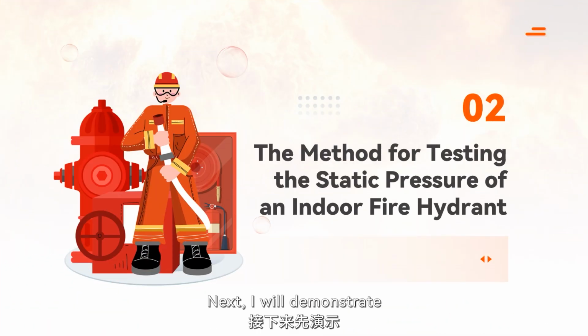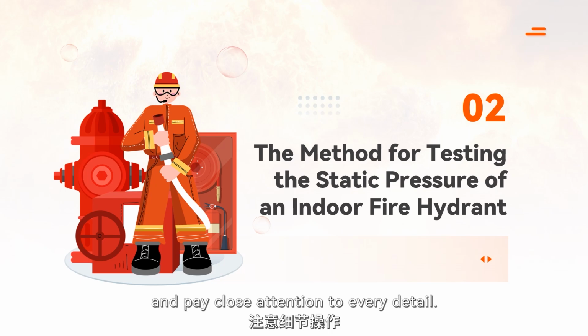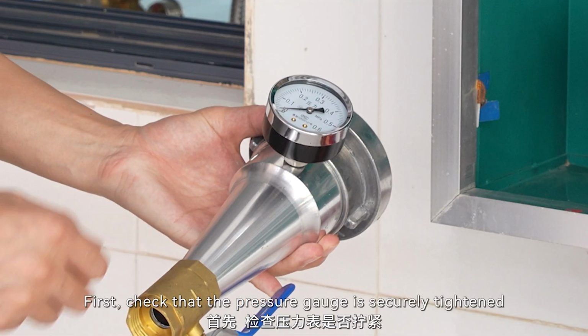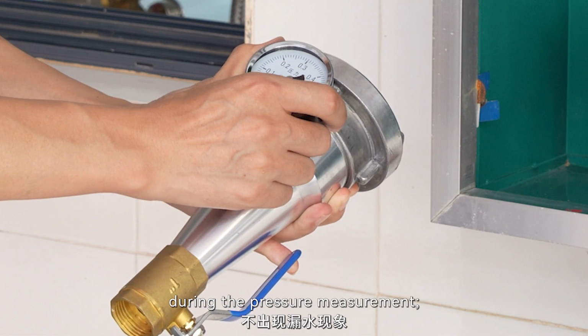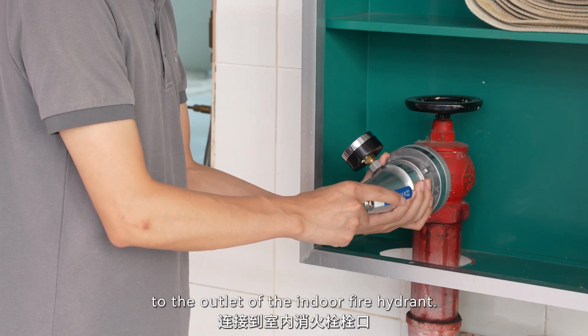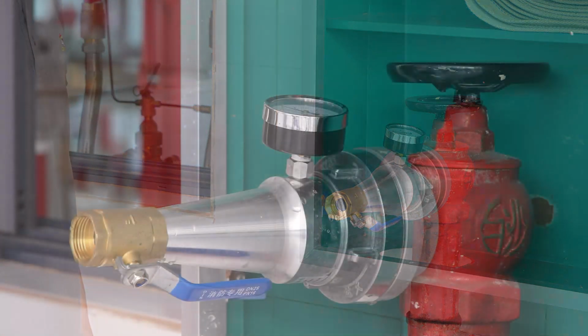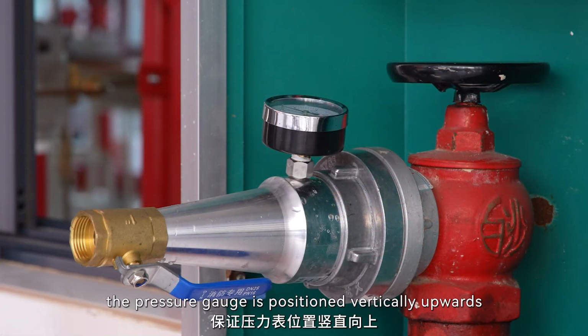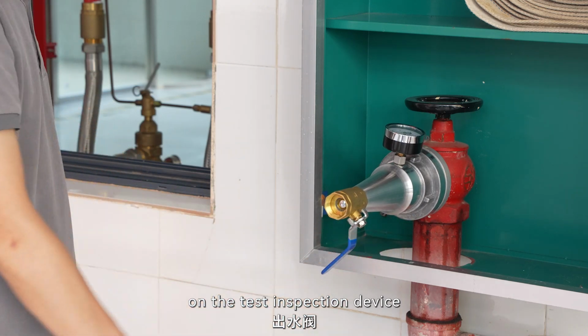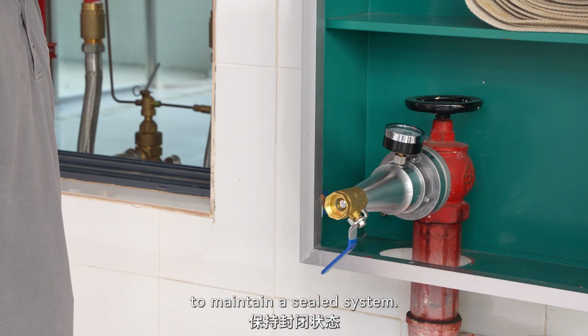Next, I will demonstrate how to test the static water pressure of an indoor fire hydrant. Please study attentively and pay close attention to every detail. First, check that the pressure gauge is securely tightened to ensure that no water leakage occurs during the pressure measurement. Second, connect the water test inspection device to the outlet of the indoor fire hydrant. Ensure that when installing the device, the pressure gauge is positioned vertically upwards to facilitate accurate readings. Then, close the water outlet valve on the test inspection device to maintain a sealed system.